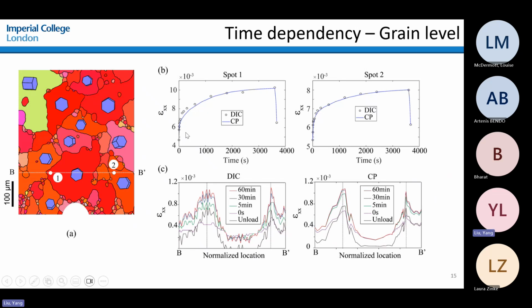And this accumulation of the creep strain could not be ignored because near the notch, a little bit away from the notch 1 and 2 position, the creep strain accumulation is more than 50%. That means that if you have a notch inside the cladding tube material, it's going to be creeping much when you're holding the material at a longer time scale.